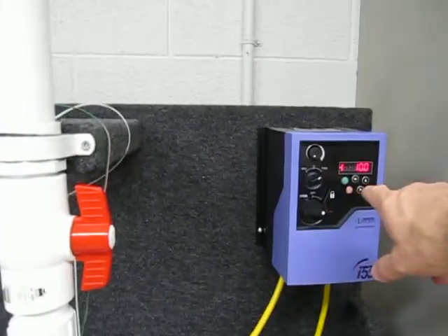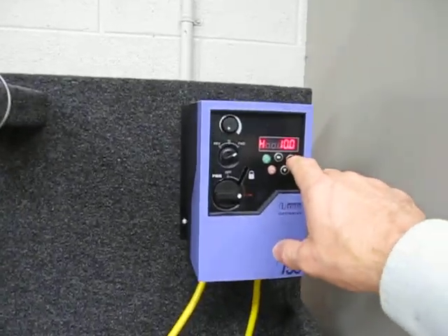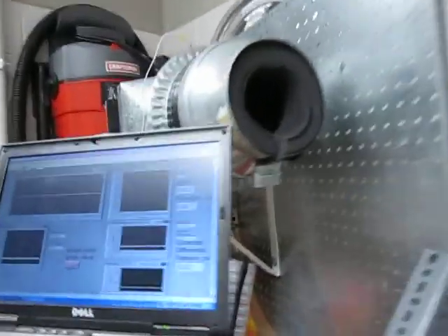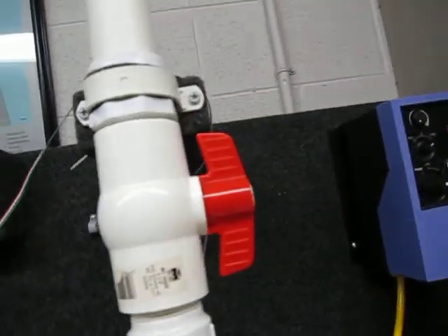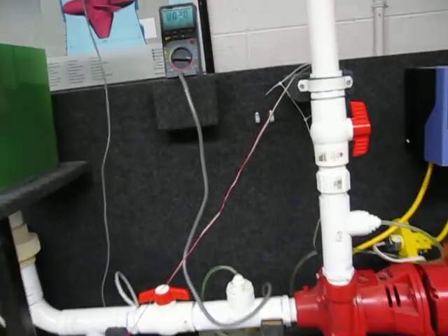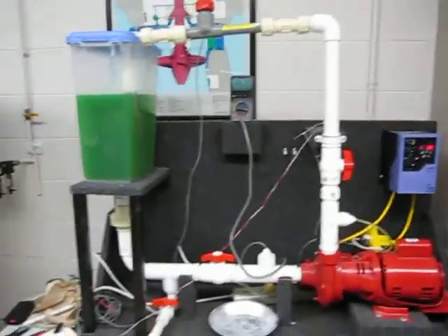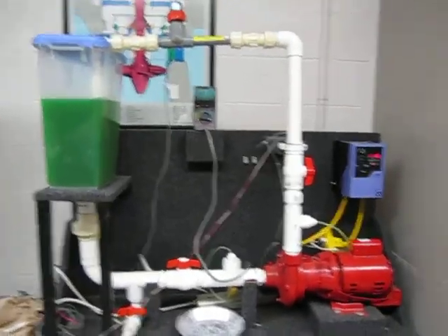So we set this at 0. Actually it goes down only to 10 Hertz. That's as slow as it's going to go. But we'll see we get no flow, and record the pressure difference, which is 0, record the power that's used, which is very low. So this will all get written up, and what's going to happen is we're going to find the efficiency of the system.